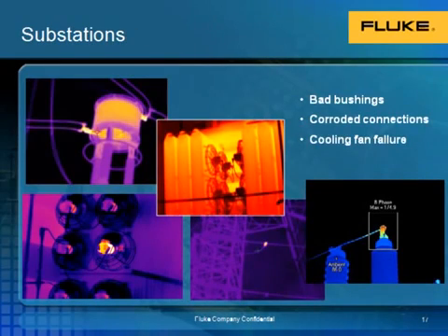When it comes to substations, resolution can be a factor as well. So make sure you have enough resolution to complete effectively the task at hand. Now obviously substations are the responsibility of the utility company to maintain. However, in many cases, companies that rely, as most, on a lot of power throughout the day will actually take their thermal imager out and just give the substation next to their facility a quick once-over, because they know if they're able to catch a problem even before the utility, it prevents them from having any downtime. So again, if they can catch a problem and have the utility company fix it before it actually fails, they have saved themselves some money.